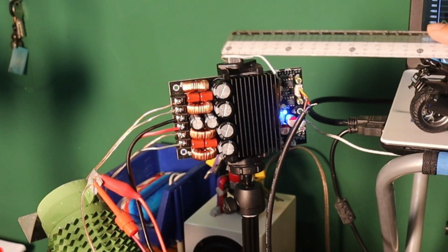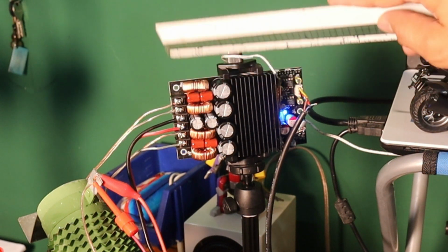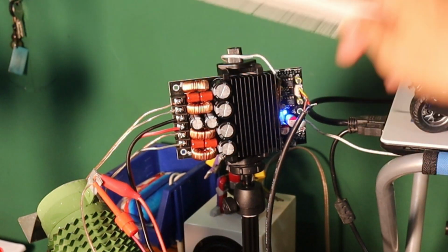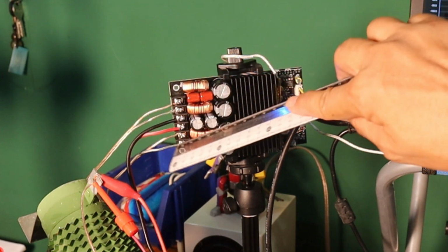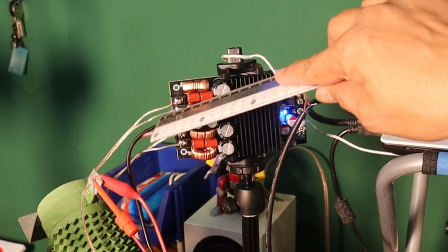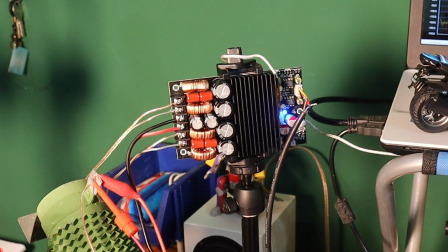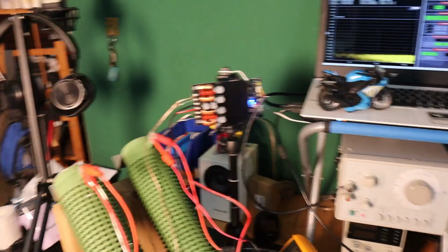But my understanding about Class D BTL, the bridge-tied load, is that both the left and the right channels are actually not referenced to ground. That is why I put it in the same way. This is the live one. This is also the live one for the right channel. And this is supposedly for the GND. Let's just say like that. And I put it in the same way. That is a uniform connection that I've been using in the SE mode, the single-ended. And my connection should be right. Also the way I put,